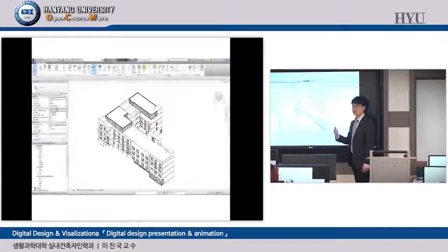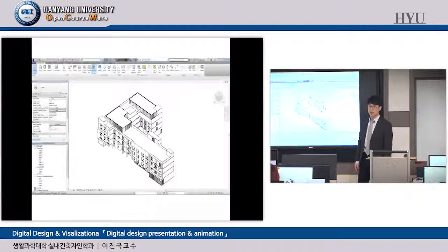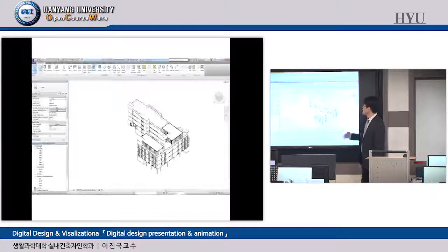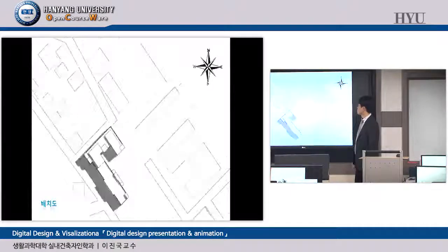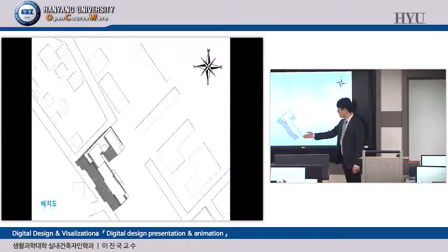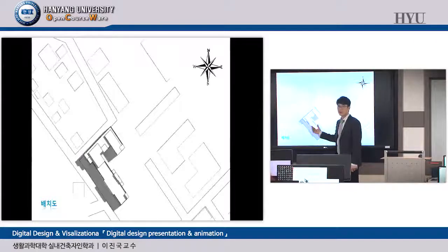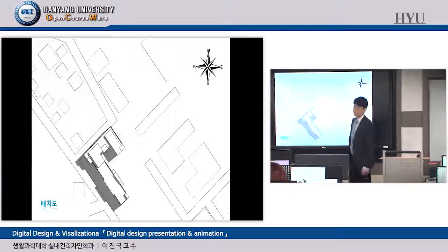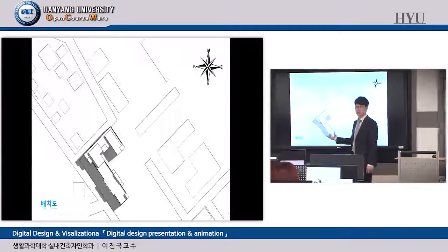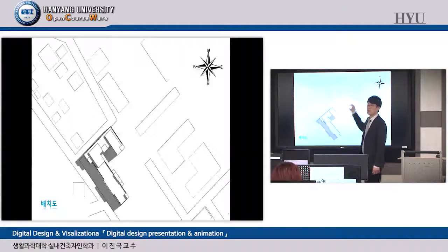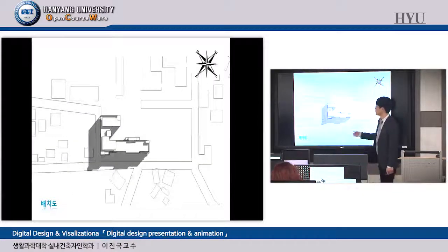You're going to be asked to model something like this in today's lab exercise, okay, for this building. Series of visualization examples. Site plan with shade. So is this shade just for visualization purposes? No, this is a precisely measured real shadow, because Revit knows the compass, where the north direction is, and Revit knows where the sun is, if the time is assigned, okay? So something like this.